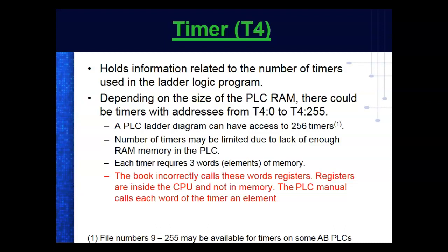But the fixed PLC, the 1000, you cannot add more data files. We can with the 1100. So that might not be available on all of the MicroLogix PLCs. The number of data files may be limited due to the lack of enough memory in the PLC.